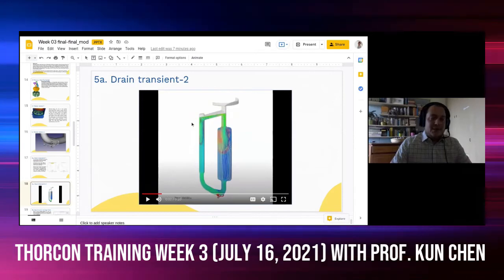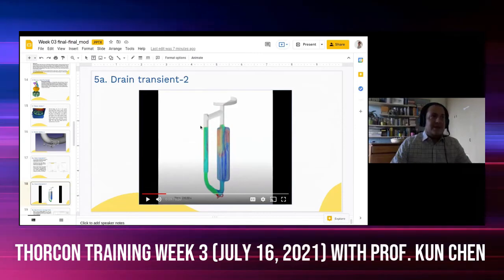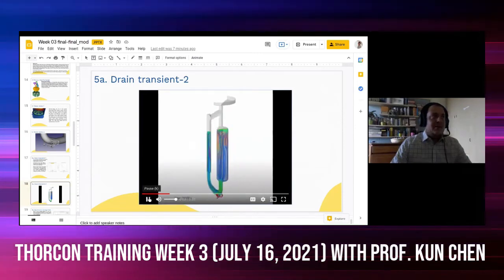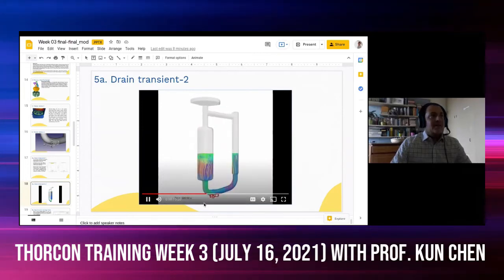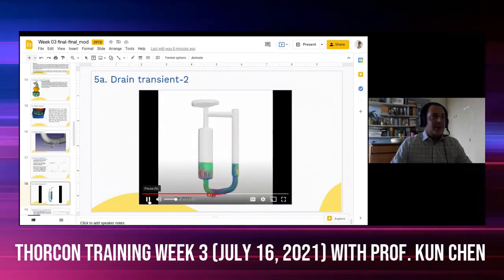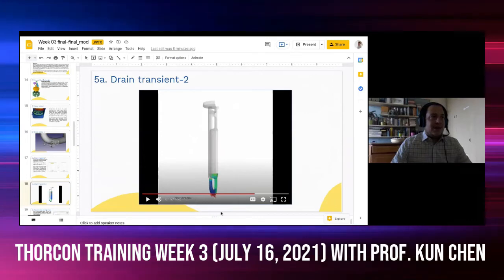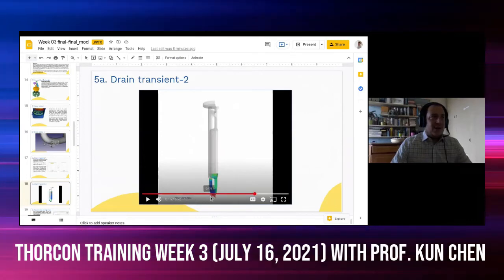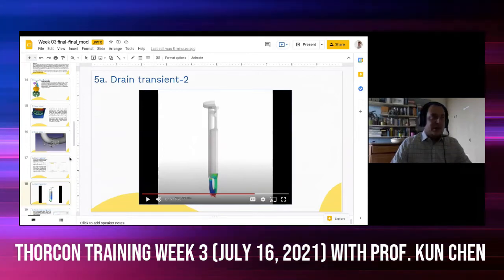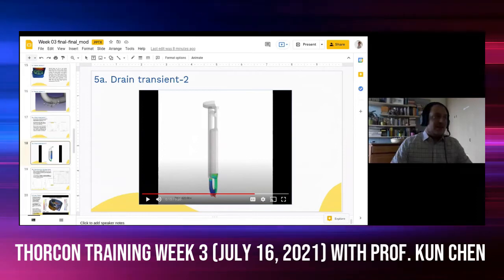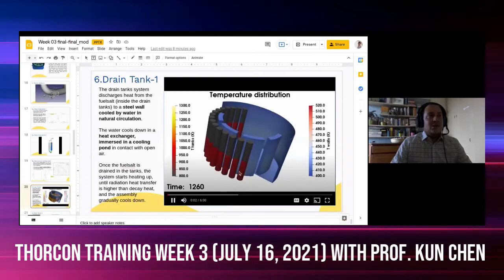Then the pipe completing the primary loop below the valve. Then the primary heat exchanger is emptied. And finally, the core empties. These all happen in approximately 600 to 700 seconds. And the flow of salt is stopped after 700 seconds, and all the salt is in the drain tank. The salt in the drain tanks evacuates heat mainly due to radiative heat transfer.